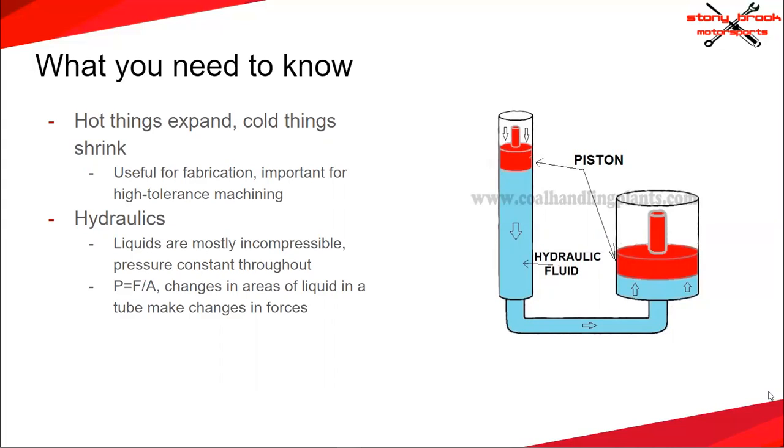It's also really important when you're machining, especially if you machine a part and it's too hot. As the part cools down, it'll shrink and you can get a part that's really undersized. Not as important for us, but especially if you're going for something like aerospace manufacturing, very important.